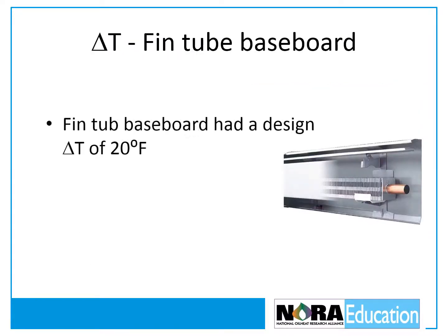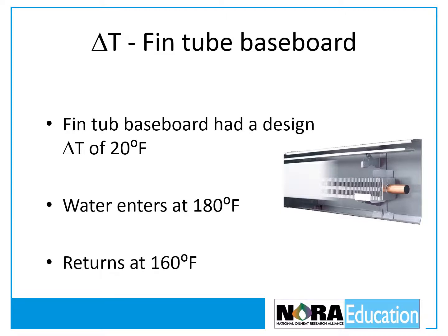Fin tube baseboard has a design delta T of 20 degrees Fahrenheit. This means that water enters the zone at 180 degrees Fahrenheit and returns at 160 degrees Fahrenheit, 20 degrees cooler.